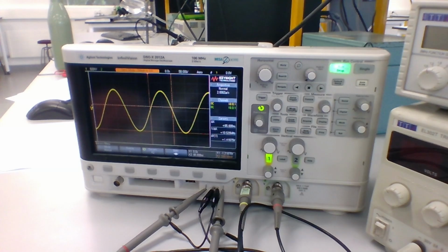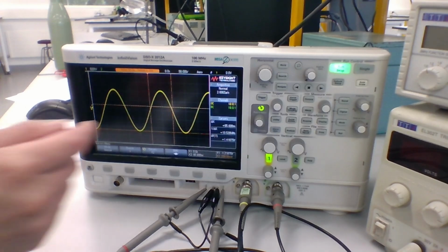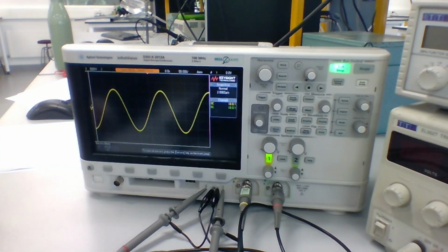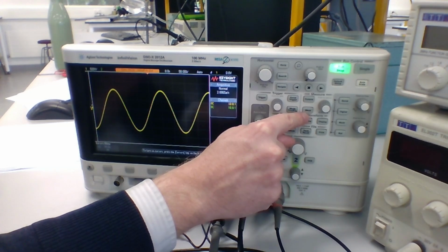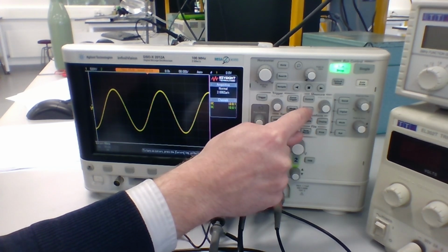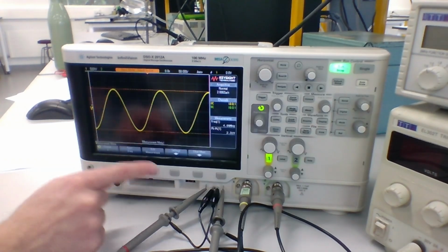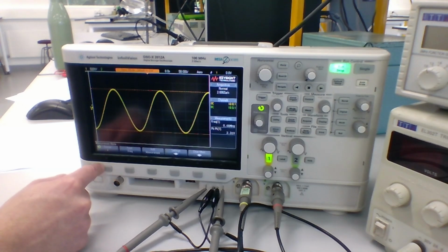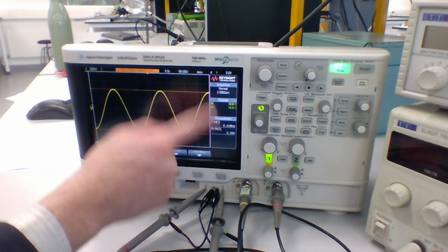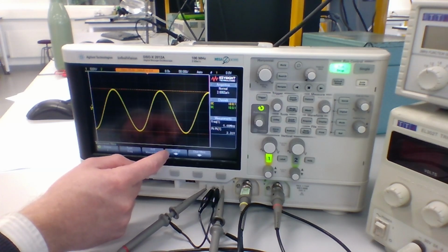Okay. The lab manual doesn't talk about this, but I will show you a third way of taking measurements on the oscilloscope. I'm just going to turn the cursors off so it's a bit clearer. The third option we have, if you look under the measurement menu here, is this button labeled MEAS, M-E-A-S. This brings up a menu of measurement options. Here we can select different types of measurements on each channel and add those so we can read out different things going on the oscilloscope.